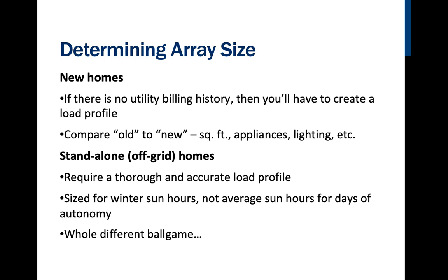Then we're going to take that number and size a battery pack. And the battery pack, again, we only have 50% available to us, and so we already have to double the size of the battery pack. Plus, we're going to have 3 or 4 days of autonomy. So we take the battery pack that we originally sized for the needs, then we double it because we only have access to 50% of the capacity. Then we multiply that by 3 or 4 so that we have 3 or 4 days of